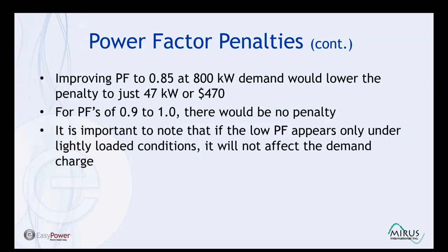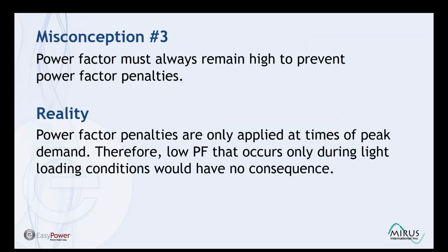What we need to make sure is that when we're at our demand load level, our power factor is above the minimum power factor requirement. So our third misconception is that power factor must always remain high to prevent power factor penalties. Power factor penalties are only applied at times of peak demand. Therefore, low power factor that occurs only during light loading conditions would have no consequence.